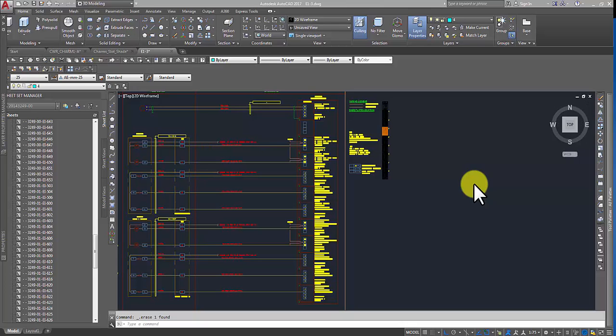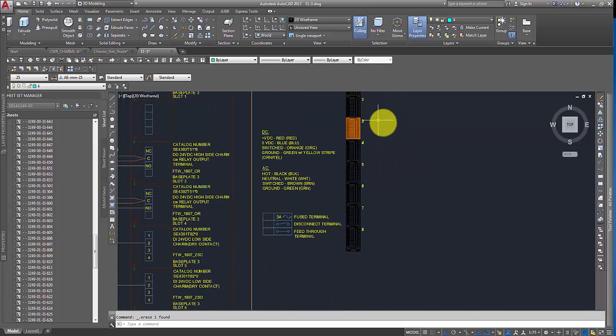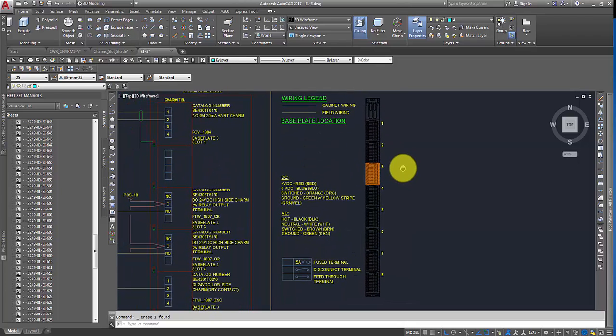Hello. So one of the common things that we need to do with PLC diagrams is actually create a shade on the actual layout of the PLC so we can identify clearly what card on the rack we are talking about with respect to the loop drawings for that particular card. So often what we do is put together a shading across the actual rack itself.